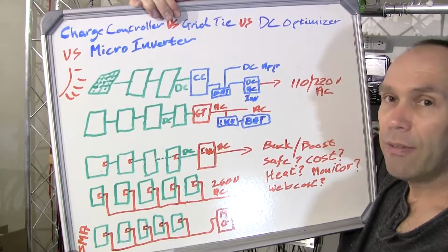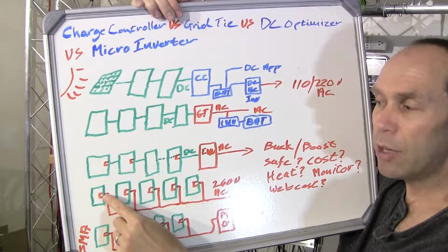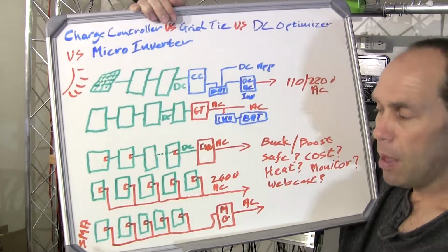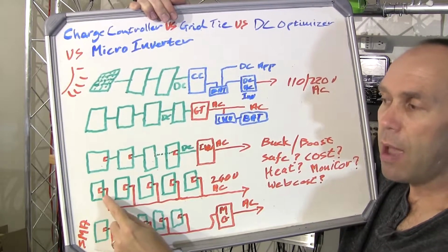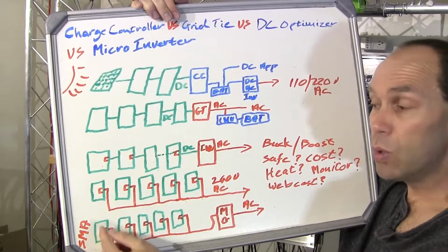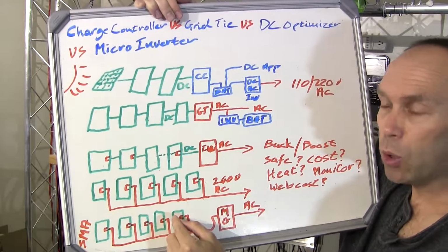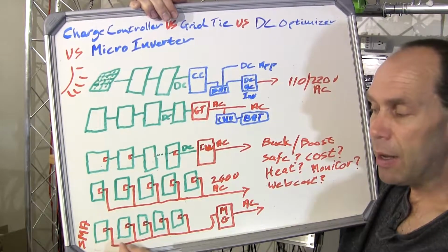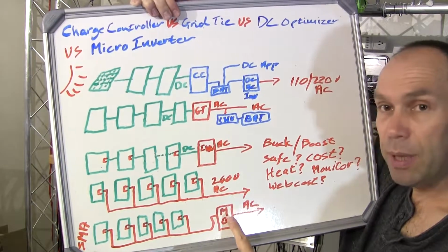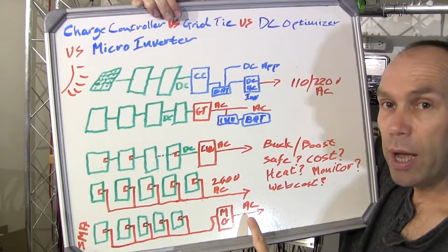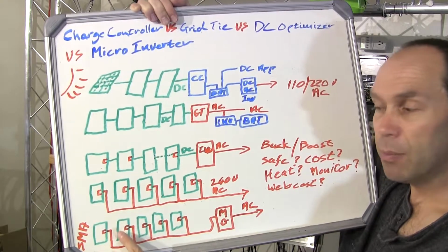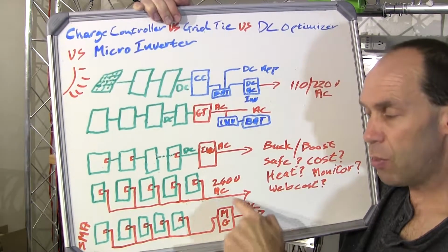What some manufacturers have elected to do is split off some of the electronics from those microinverters. As an example, I'll talk about SMA. They also have microinverters that they've literally just brought out in the last year. Their microinverters will do MPPT and optimize each panel for you, and they'll generate AC onto a common bus. They have something called a multi-gateway, and that needs to be there to finally provide the AC to your house. They say by doing this, they're removing some of the electronics which are at risk to heat behind the solar panels and bringing it to a central point over here.